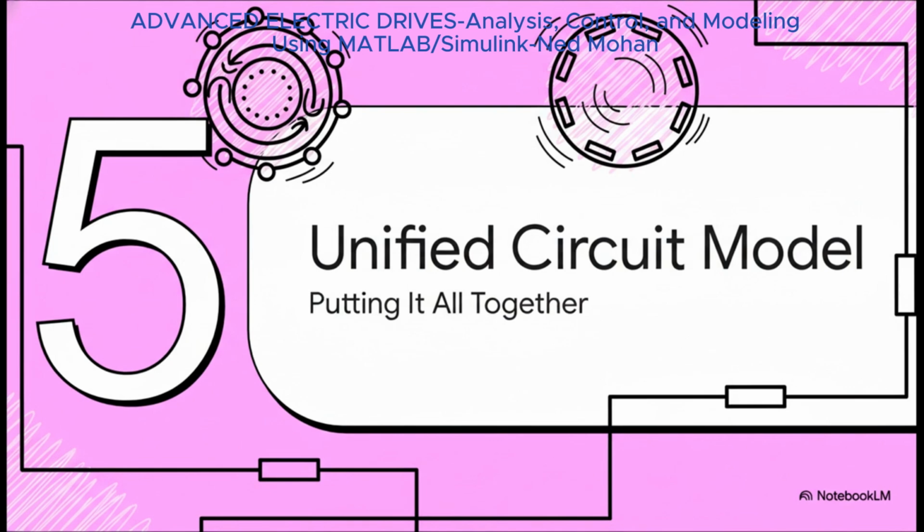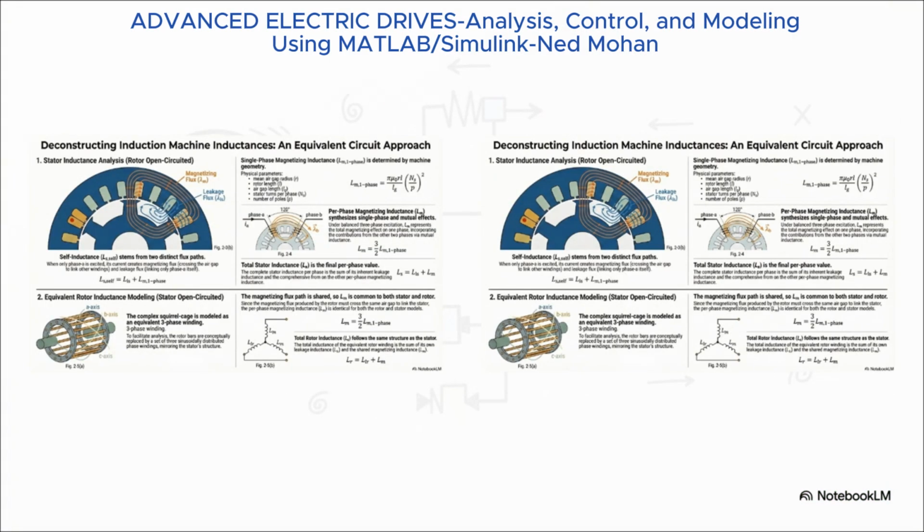We've got a model for the stator, we've got an equivalent one for the rotor, and they're both built around a common element. So let's put it all together and see what the final unified circuit looks like. And there it is. You can see the per-phase stator circuit and the equivalent rotor circuit right next to each other. They look identical, don't they? And that shared inductance, Lm, that's the magnetic bridge that couples them together, just like the air gap flux physically couples the stator and rotor in the real machine.